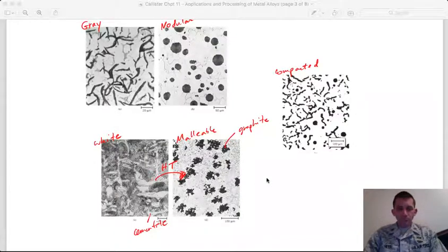So like is typical with a lot of different metals, if you quench, you get a hard but brittle material, and then heating it to a higher temperature and holding it there, you allow some of that stress to relax, some diffusion to occur, and oftentimes, as you see here, you get a different microstructure that regains some of that ductility at a cost of some of that hardness.